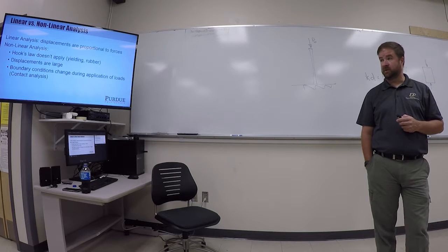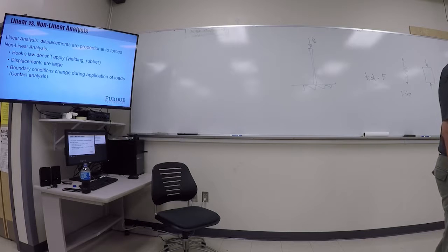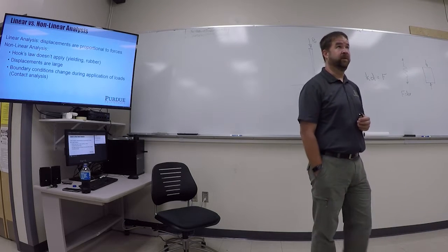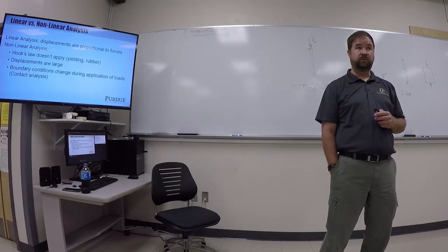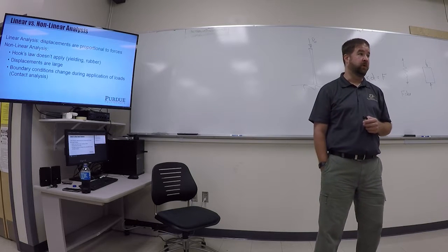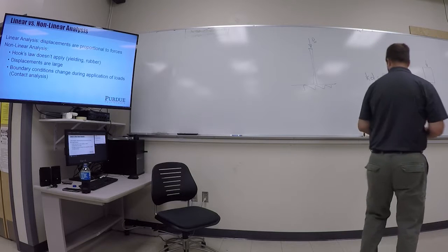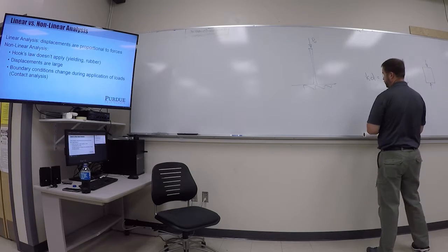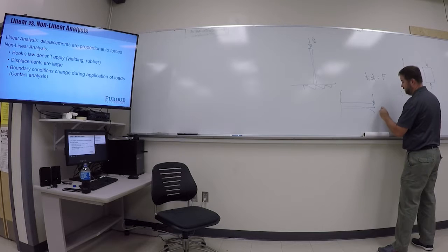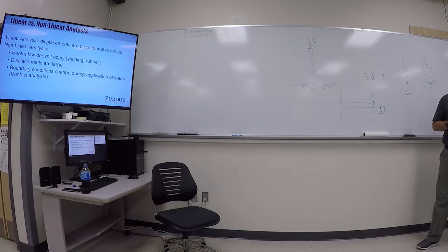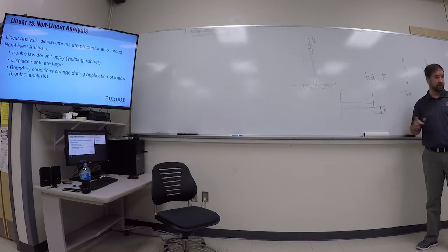Other nonlinear analyses are when displacements are very large, something we haven't talked about, or maybe a reminder back to strength of materials. Those equations that we use assume that the displacements are small. Okay, so if I'm looking at the force on the end of a cantilever beam, and I want to know how much it deflects, the assumption built into the equations is that this deflection is small. And what exactly is small? Well, I don't have a real good definition of that for you, but orders of magnitude smaller than, say, the length of the beam.